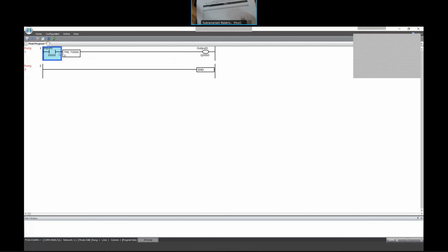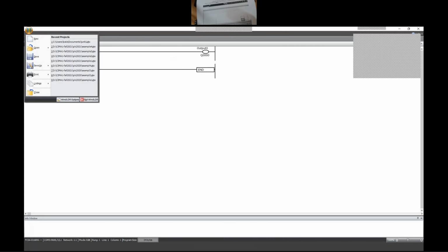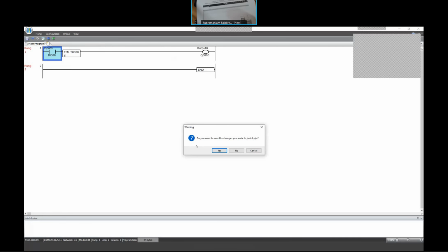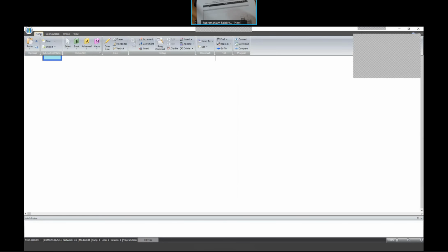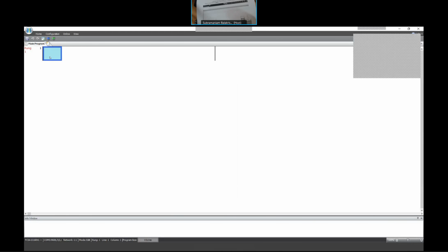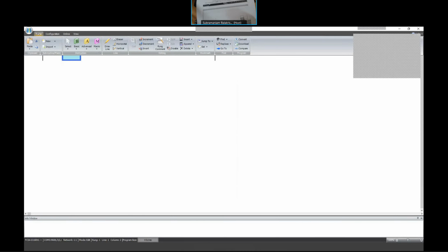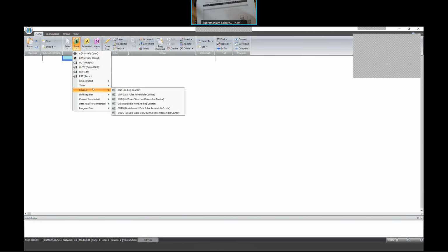Okay, what should I do? All new. I want to save this. Okay, so home, basic, normally open. I'm not putting any address to it right now. Here I am going to say, basic. We did normally open, normally closed as input and output, and now I am going to go straight to the counter. I'm going to take the adding counter.